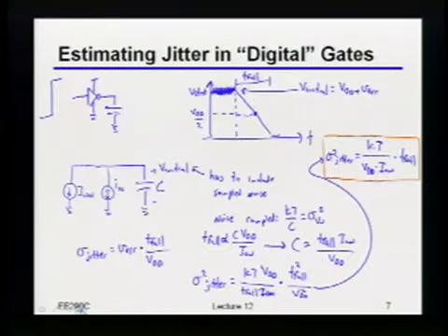So what we ended up on last time was, for the purpose of giving you an example of how you go about doing some of these calculations in terms of jitter, or really more importantly, translating thermal noise into timing jitter, showing how, even for the simple example of an inverter, you could figure out how the thermal noise of that inverter was going to be translating into timing error. Okay? So we said there were two important components there.